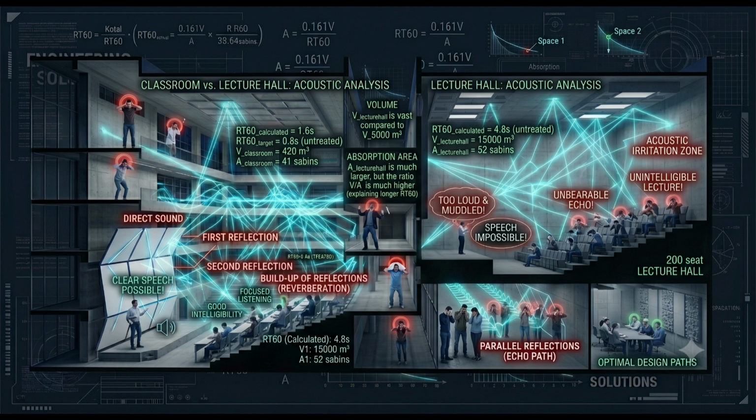For example, a massive stone cathedral might have a reverberation time of 7 seconds, which sounds beautiful for choral music. However, a productive meeting room or a classroom needs to be well under 1 second. Spaces with excessive reverberation get incredibly loud because sound waves continuously bounce off hard surfaces. This creates an echo effect that distorts speech intelligibility, making it highly difficult to understand a teacher or speaker in an auditorium, a gymnasium, or a hospitality space.